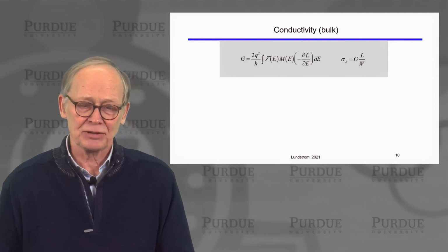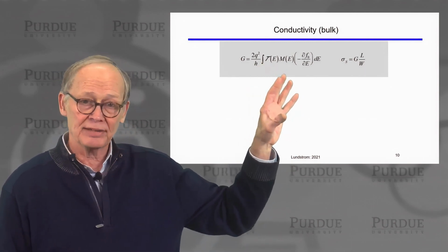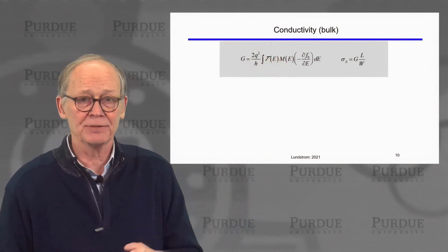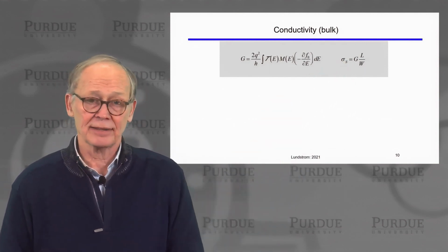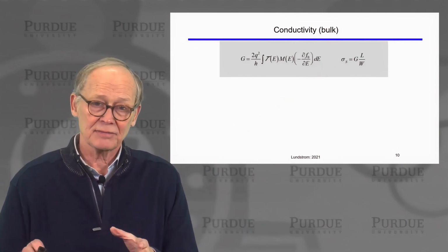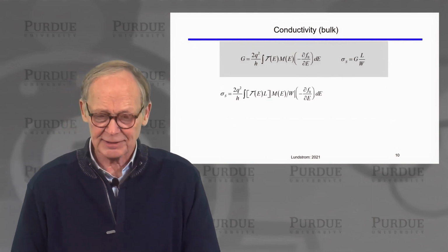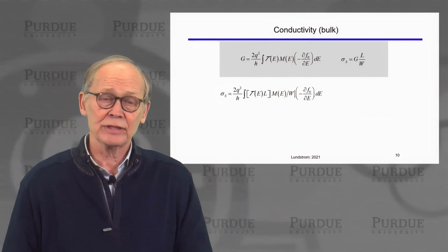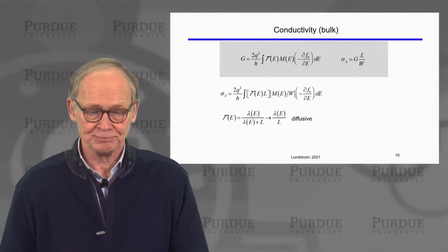All right, so how can we use this information? We have an expression for the conductance of an arbitrary material in terms of its transmission and number of channels. And we have an expression for the sheet conductance. Given the conductance of a large device, we can deduce what the sheet conductance is. So if we just equate those two, we'll get an expression for the sheet conductance that we can work out.